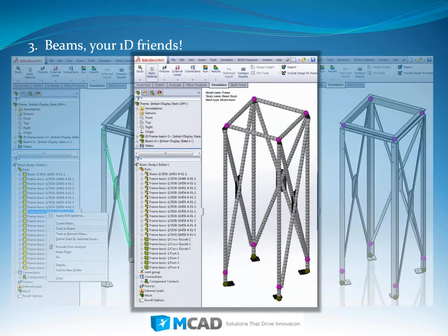And if we were to mesh that, here we see the representation of the solid and beam mesh, and that's very much less overhead involved in solving this model. And in fact, some models, it's nearly impossible to mesh with solid elements when you have these types of members. The cross-sectional thicknesses are just too small to get a solid element through it.